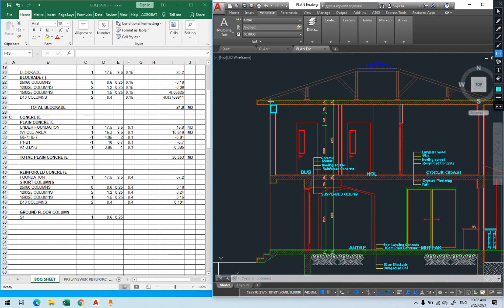Now, when the dimension of the beam is given to us, let's say this is the beam, the dimension of this beam will be given in this manner. Let's say it's written 25 by 60. So this 60 is the total height of it. That's the other reason we want to calculate from here till the top: if I know this one, and I take out this one, I can get the column's height easily. So we have 3 meters for the 2 stories, and if you know the depth of the beam, I can get the height of the column.